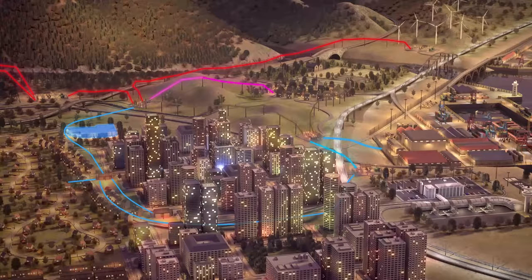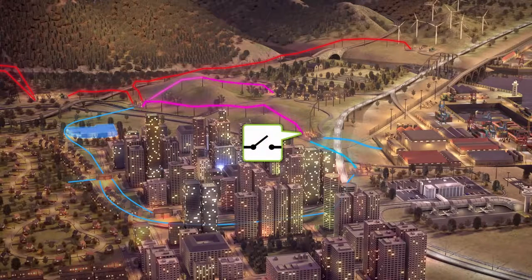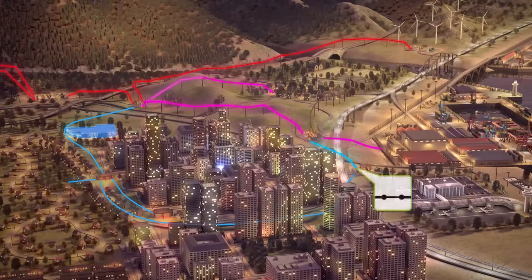The newly repaired line is tested first by closing the primary substation's outgoing switch to substation 2. The line energizes as normal, confirming the repair. The operator can now close the incoming switch to substation 2, reinstating the original supply route. The backfeed from substation 3 is no longer required, and so the SCADA operator can open its outgoing switch.